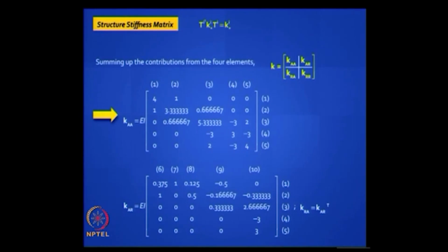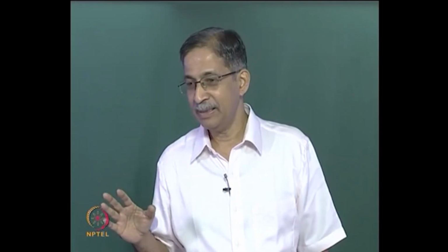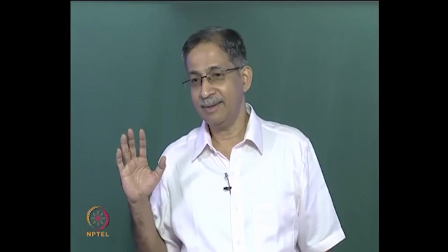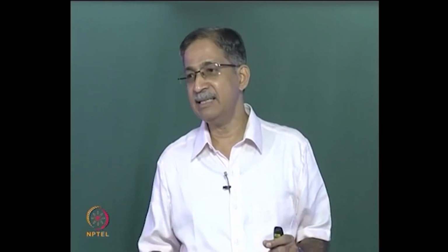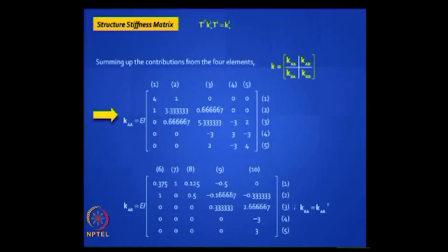It means all the diagonal elements must be positive. If any one of them turns out to be negative, you made a mistake. Another thing to look out for is, if any of the diagonal elements is close to 0, you have got an ill conditioned matrix. Inverting that matrix will give you a lot of errors. Normally it will never happen, because luckily for us, in linear elastic structures the stiffness matrix, unlike the flexibility matrix, is guaranteed to be positive definite and well conditioned.